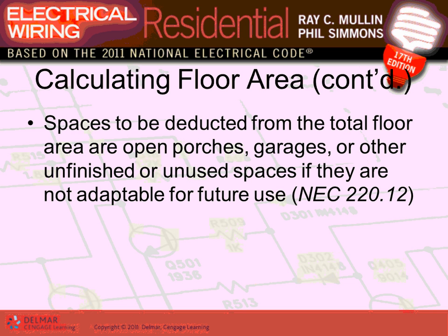Okay, we went to table 220.13, guys. Deduct from the total area what's not habitable. Look what we deduct: porches, garages, or any unfinished basement, unused space, if they are not adaptable for future use. When you sit for your master exam or journeyman, they catch you on that one. They say, is the basement included? No, basement's not included. No, it is included.